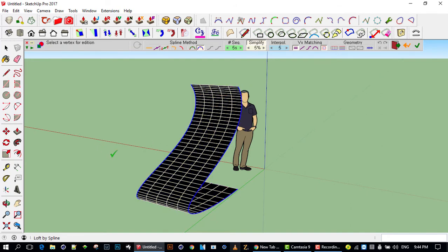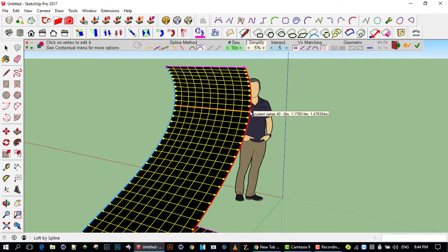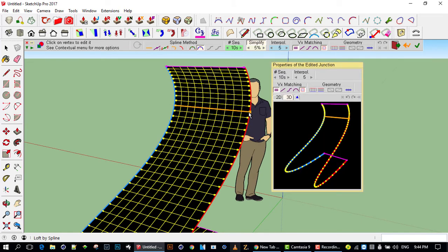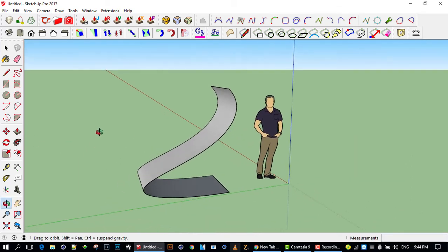And you can see the potential here, because now you can create different Beziers. And maybe I'll just show another example, but this is what it does. It takes a spline, which is a single line, and then joins it to another single line. And here you can do all the settings. You're creating more segments, etc. When you're happy with it, it shows the tick mark when you're on there. When you're hovering over it, you can select edges and move and edit edges along the way if you want to. But for now, I'm going to just complete it, click off here, and there I've got it.